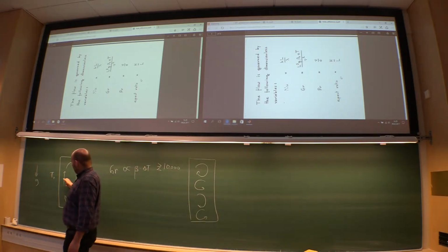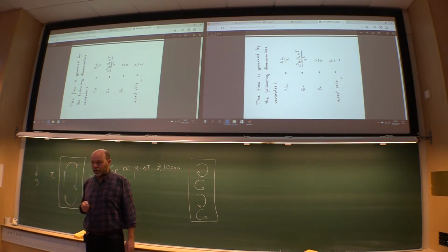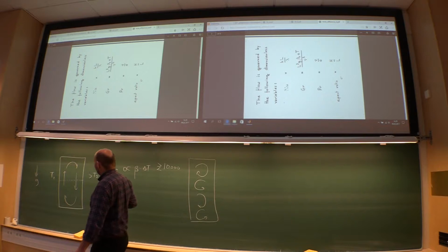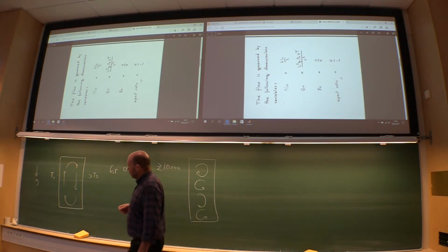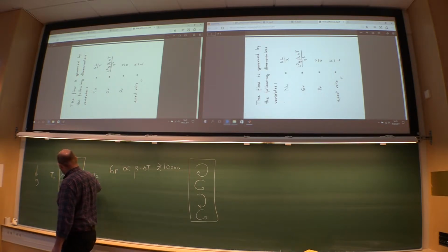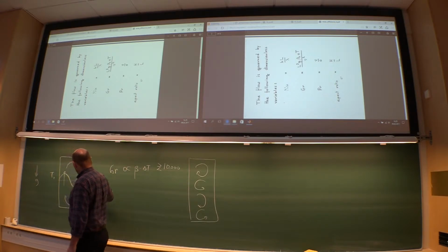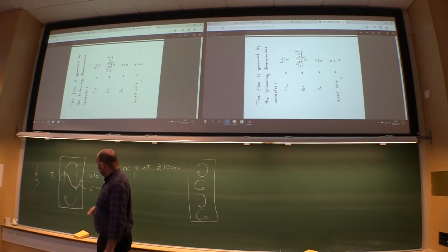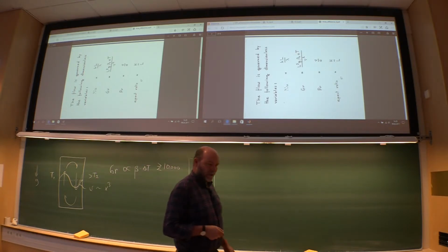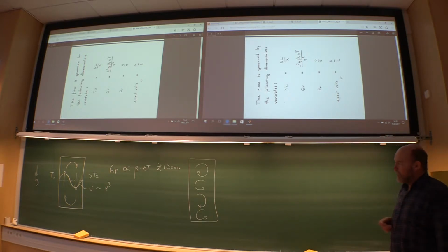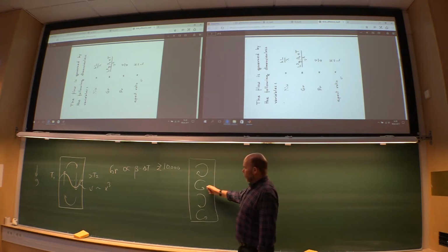For this case, you have a very nice analytical solution given by Batchelor. If you take a cross-section here, the velocity profile will actually go as x to the power of 3, and it should go to 0 at the walls. So the v velocity goes like x to the power of 3, and the temperature varies linearly from wall to wall. But that system breaks down when you have too strong a driving force.